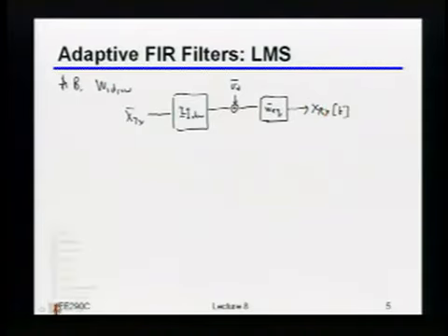So to see how we can figure out how to adapt that equalizer, whose coefficients will just be the entries in this W vector, let's take a look at what it is that I actually receive. In other words, what is that actually comprised of? As should hopefully be clear from the diagram, the analog voltage that I'm receiving is essentially my equalizer, transposed, because you can think of it as doing a convolution.